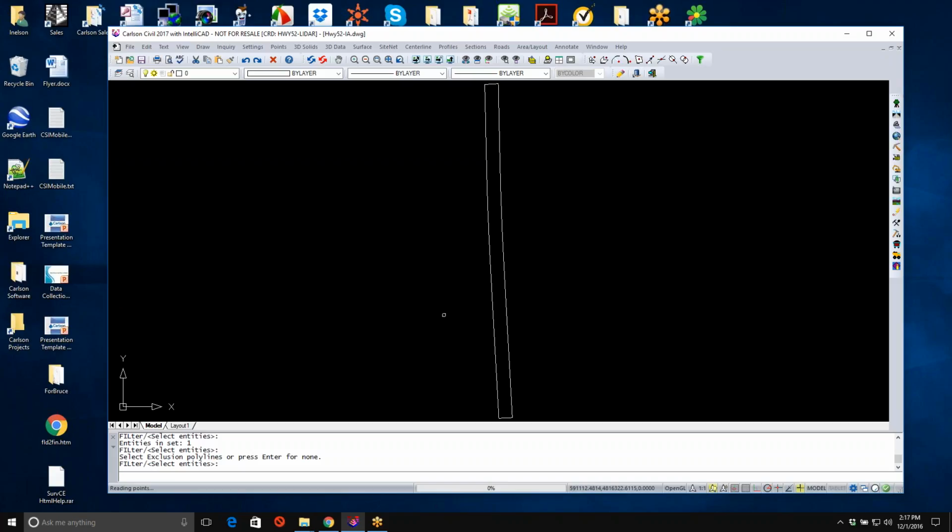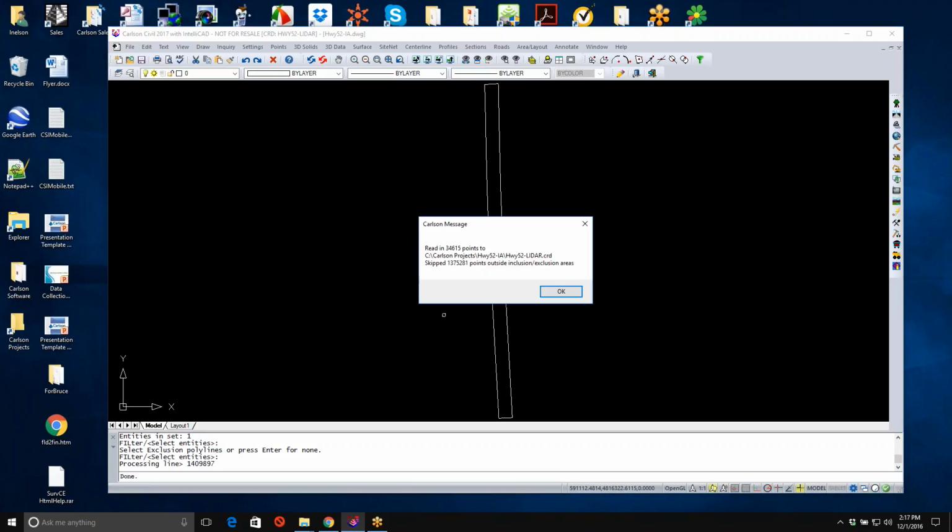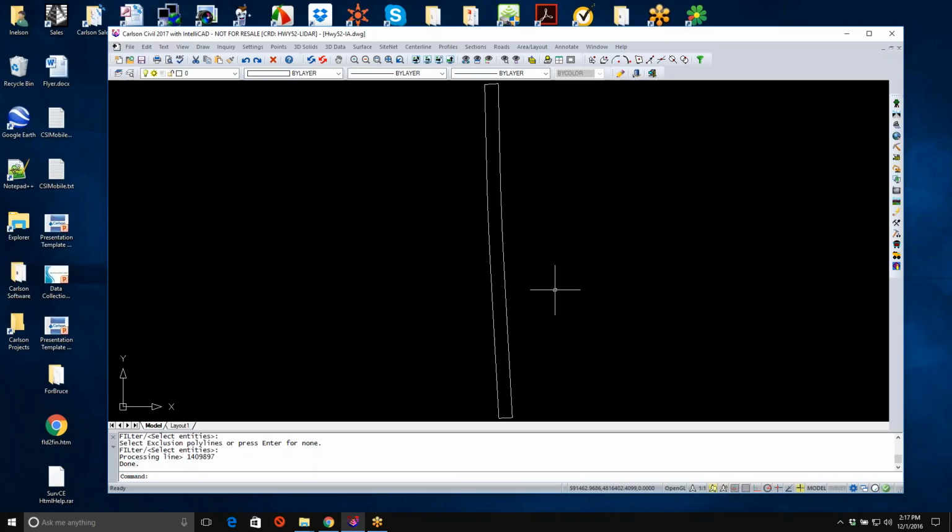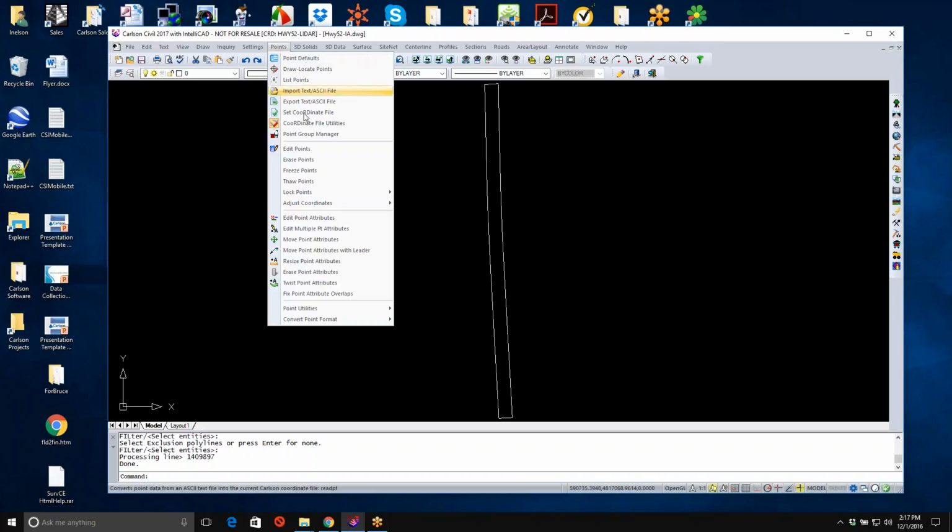Now again, with this data being in a metric system, what we're going to want to do ultimately is convert this into a coordinate system that I want to base my roadway designs on for later projects and discussions that will follow this video. I've read in a little over 34,000 points. I'll choose OK. What I want to do now is convert from UTM zone 15 into an Iowa regional coordinate system zone. To do that, I'm going to go to my points menu, say adjust coordinates, and we're going to do a coordinate transformation.